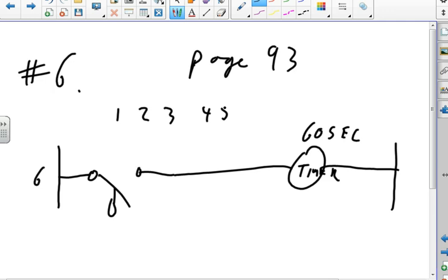And stops when the liquid reaches the high level. All right, so we're going to want a high level switch that's normally closed. So this is a low level switch.